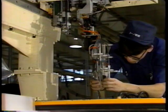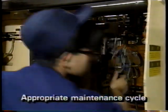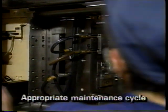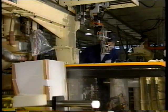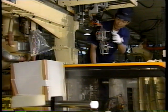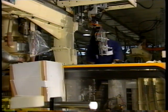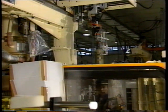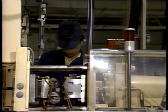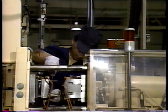By considering how to react to the natural deterioration cycle, and by deciding a suitable maintenance cycle, according to the equipment and the parts, you must implement your maintenance procedures, such as repairs and replacement of parts. By doing this, breakdowns can be avoided, and when equipment lasts longer, it's possible to extend the maintenance cycle of the whole factory. Moreover, because breakdowns are reduced, there is a drastic decrease in maintenance expense, such as repair costs.